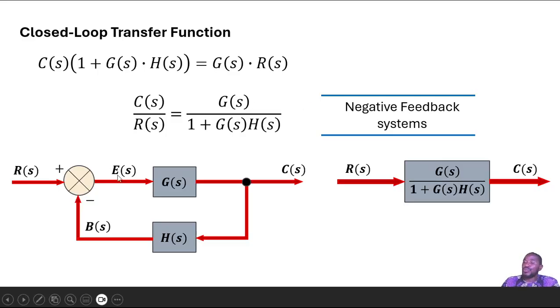Okay, so this whole system now is reduced to this simple open loop system, as it were, where this feedback system is now represented by its transfer function. The transfer function acts on this input to give you an output. Okay, and remember that it's a negative feedback system. All right. Then we'll quickly define what the error ratio is.